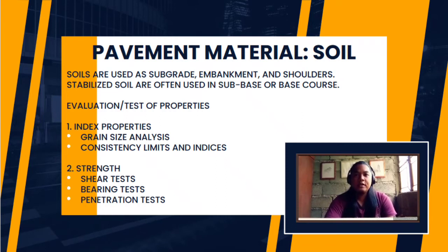Second was for the strength of soil. We conduct shear test, which is either a laboratory or field test to measure the shear strength properties of the soil or rock material or of discontinuities in soil or rock masses. And we conduct bearing tests to determine the ultimate bearing capacity of the soil. And lastly, we conduct penetration tests.